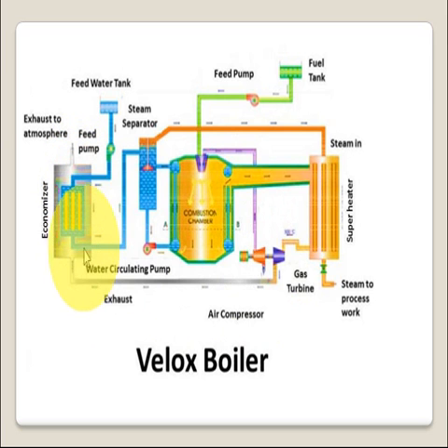Now the slightly heated water enters the steam separating drum, and from there the water enters the water tubes, where it absorbs heat from the hot gases by radiation and convection, and that hot water enters this drum where steam is separated, and that separated steam flows to the superheater where it is further heated to superheated condition, and the superheated steam is used for process.